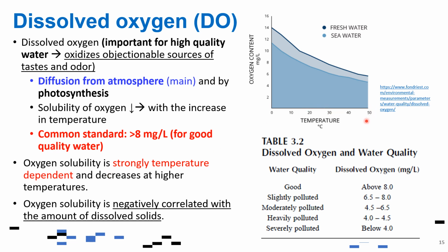Another thing with regards to the presence of dissolved oxygen in wastewater. Normally in wastewater treatment plants, they require some oxygen level to help in the degradation of organic matter, especially in the biological reactor. So that's why the oxygen level usually in wastewater is not so high. That's why aeration is usually done to give more oxygen during the biodegradation of organic matter.